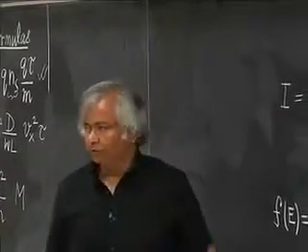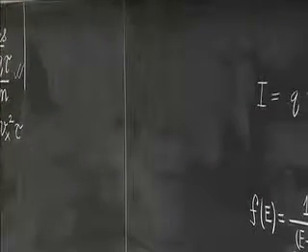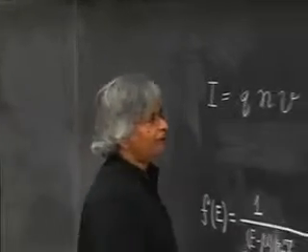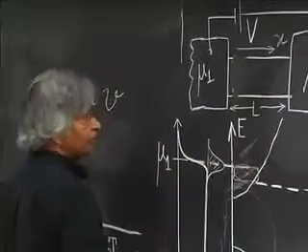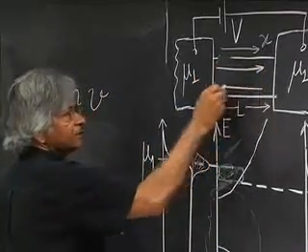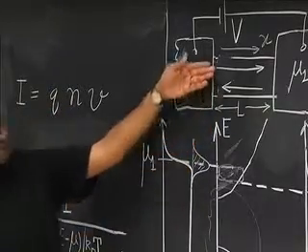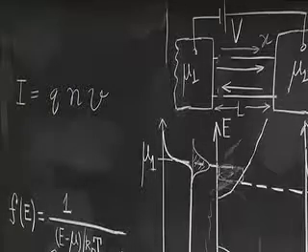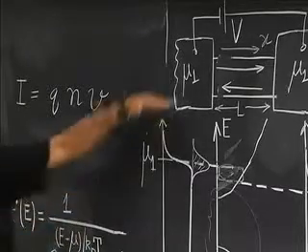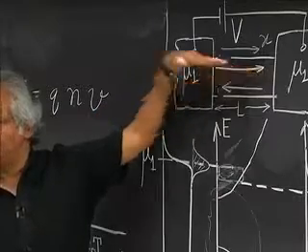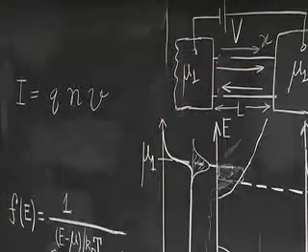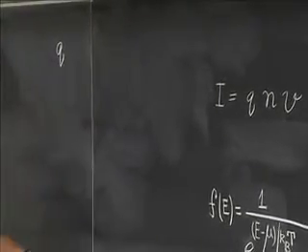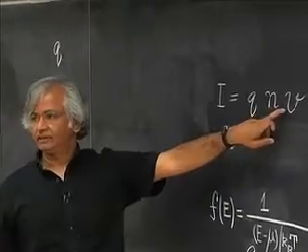So the way you can think about this is the following. We're starting from this case of a ballistic conductor where you have electrons that are going through like this, and there are electrons, you have states. Half the states are going from left to right, the other half are going from right to left. And the idea is that you could write the current that is carried by the right moving states. Those, we could write as Q times the electron density times the velocity.